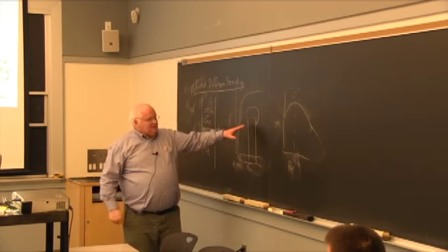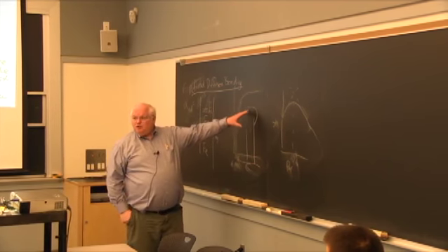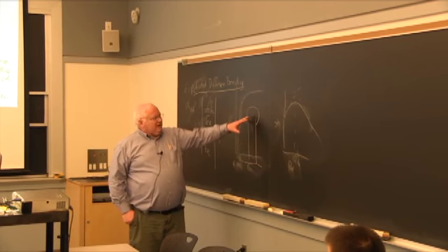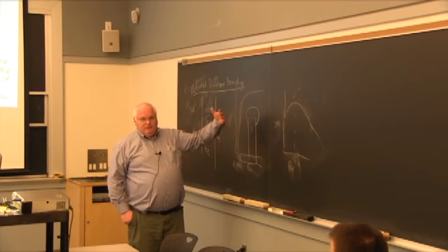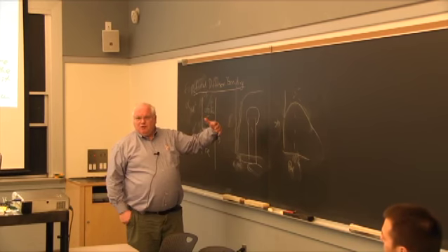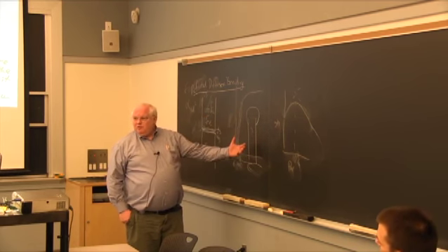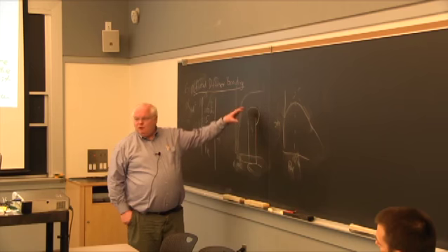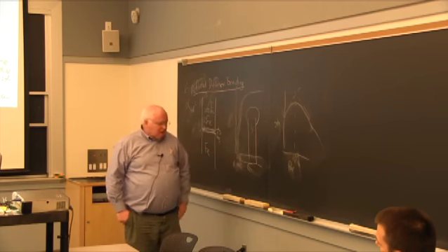Okay? If it wets, you can put larger amounts of liquid on top of the material here, but in addition, what he was really thinking about, you could think of it as if it was at the melting temperature, and so it was isothermal, but in the real life of the real experiment, it wasn't even at equilibrium. I'm putting a hot drop on top of a cold post when I'm trying to build these things up, okay, by putting little drops of solder on top of something else.